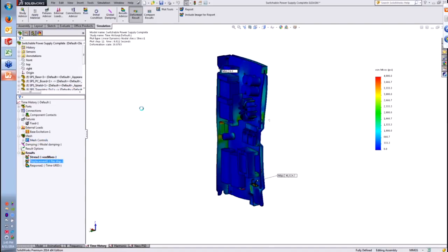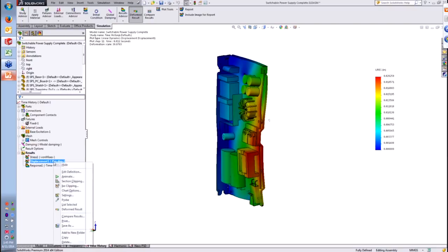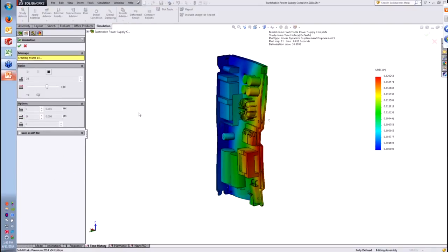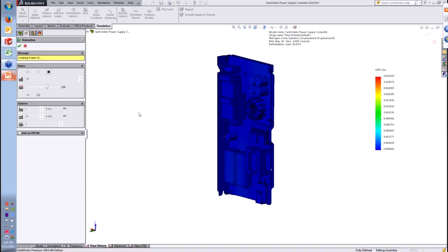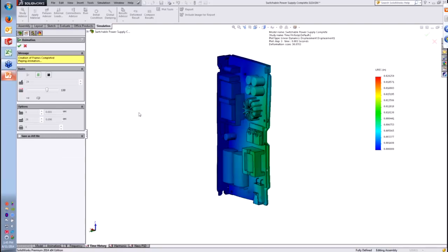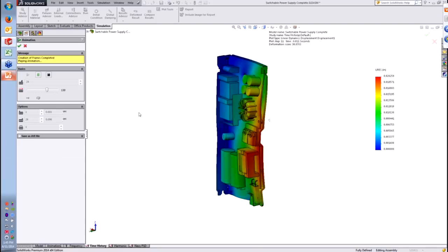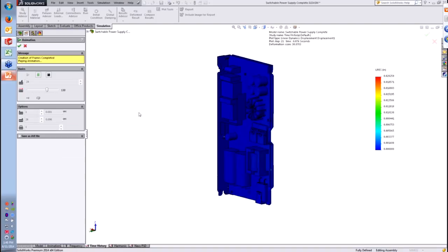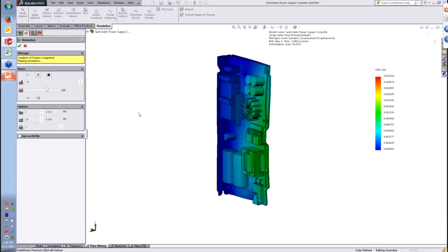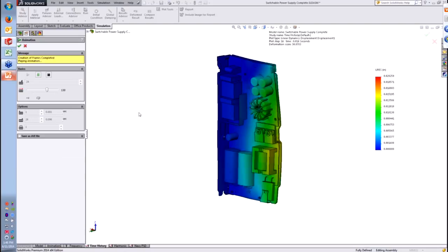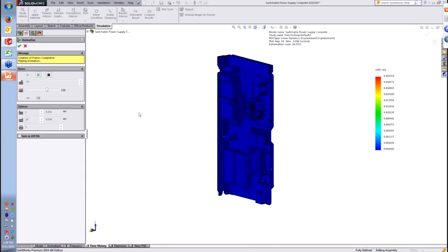We also, of course, could look at the displacement over time. So again, this analysis is showing us that at the peak of the impact, the displacement gets up to about 0.02 inches. So of course, it's still very small, which is why we're viewing this as an exaggerated scale. But that's also why it's acceptable in this case to use a linear study. In this case, it's a linear dynamic study to do the analysis.